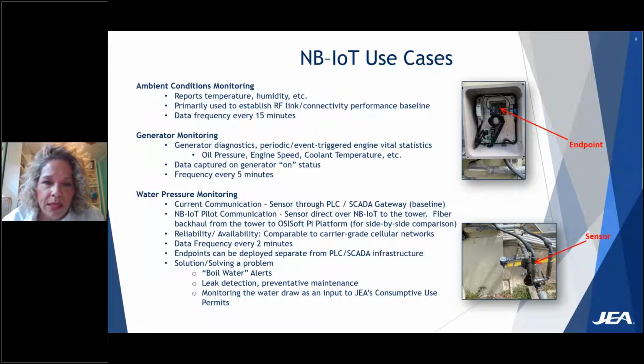Generators are pretty important to us, especially in Florida. And this year we've had a tremendous amount of rainstorms and hurricanes. So we figured that that would be a good case for us to take a look at. So we started getting generator diagnostic information utilizing CAN bus as the interface. And that has worked really well. A lot of our field personnel are able to take a look at that data and at trending information so that we're doing preventative maintenance on time.